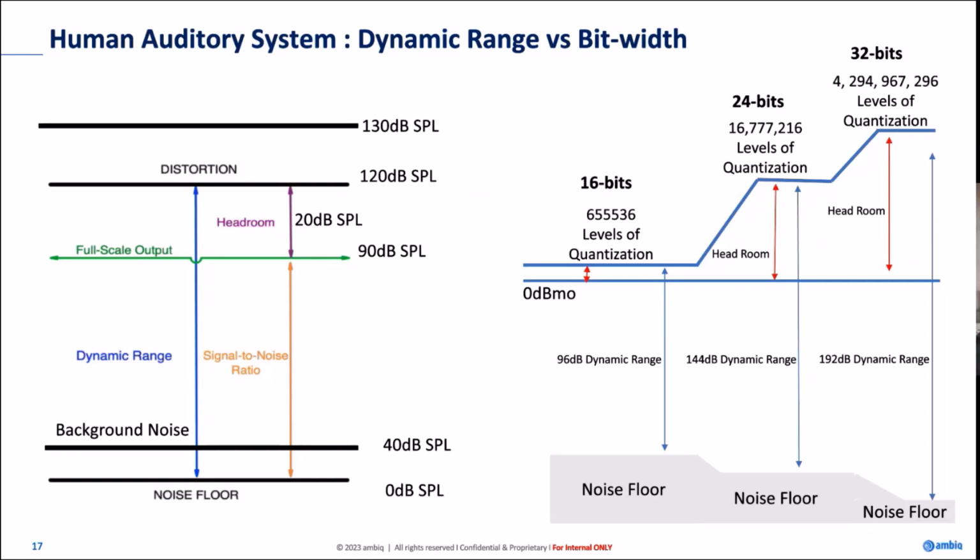So 50 dB, we can say that's floor noise. 90 dB is the headroom. So in terms of the SNR, in a typical acoustic environment, 40 to 50 dB you need. Plus, with a noise gate or noise suppression, depending on the floor noise, it can go down to 20 dB. So in total, it's about 70 dB of SNR the system needs to support.